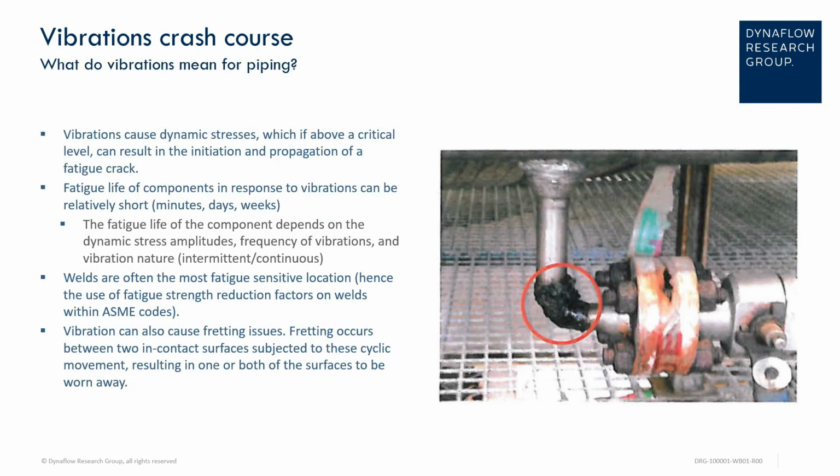Vibrations can cause dynamic stresses, which, if above a critical level, can result in the initiation and propagation of fatigue cracks. Fatigue life of components in response to vibrations varies depending on the dynamic stresses, excitation frequency, and nature of the vibrations. They can, in the end, be very short.